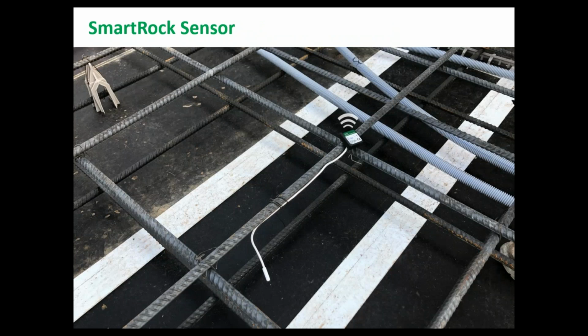But with the investments that have been happening in the electronics side and the mobile app, we've made the maturity index calculation, data collection, and analysis a lot simpler than having a wire connected to the sensor, collecting data, going to the curve, and calculating the maturity index. So the way it works is that you basically have a sensor, like a SmartRock sensor, that is fully embeddable in the concrete.